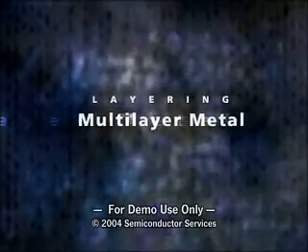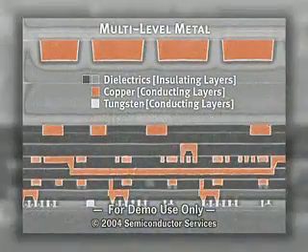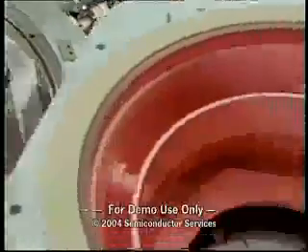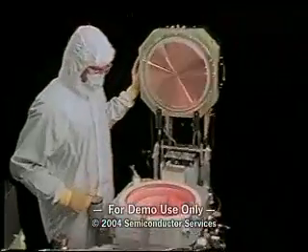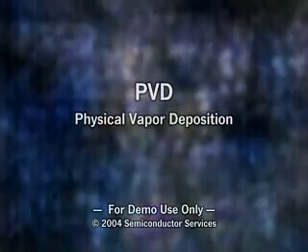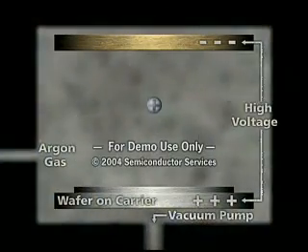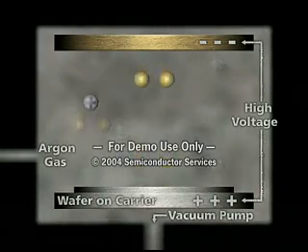Metal layers, deposited and patterned on the wafer surface, are used to connect the individual components, creating an integrated circuit. The most common deposition technique for metals is sputtering. Sputtering is a physical process and a form of PVD, physical vapor deposition. Sputtering is similar to freeing pieces from a concrete wall using a sandblaster.